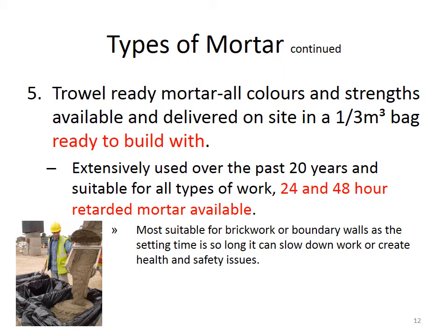It's most suitable for brickwork or boundary walls. As the setting time is so long, it can slow down the work and create health and safety issues. If you build a wall or whatever, and then a couple of days later you want to start putting the floor on top of the wall or putting beams on top of it, the mortar might not have gone off hard enough to support this after only a couple of days.